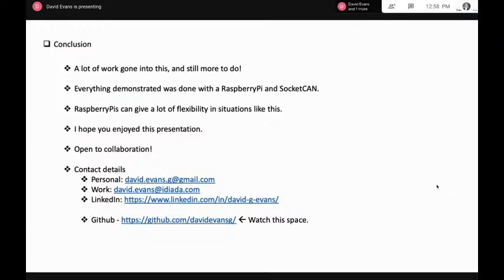One of the things I struggled with is that if I want to make a CAN message, half the battle is having some data to put into it, especially data that makes sense. So I recorded a vehicle speed value, I think every 10 milliseconds or every 100 milliseconds, and put that into a file.